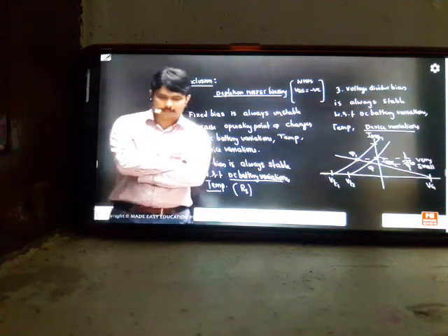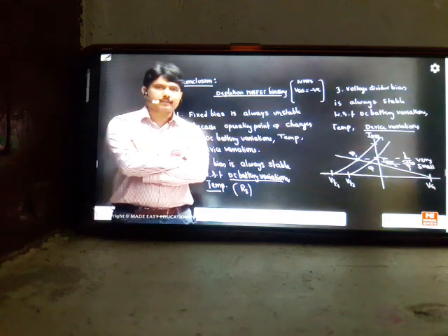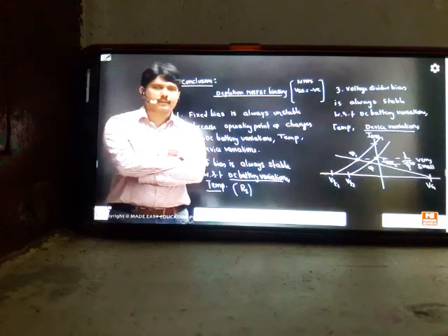Divya Das and one more person here. Majumdar, you are saying, sir, why are you using the current saturation equation? But use common sense. We are working our transistors in the amplifier region. The amplifier region in the BJT class we call the active region, but in the MOSFET classes we call it current saturation.